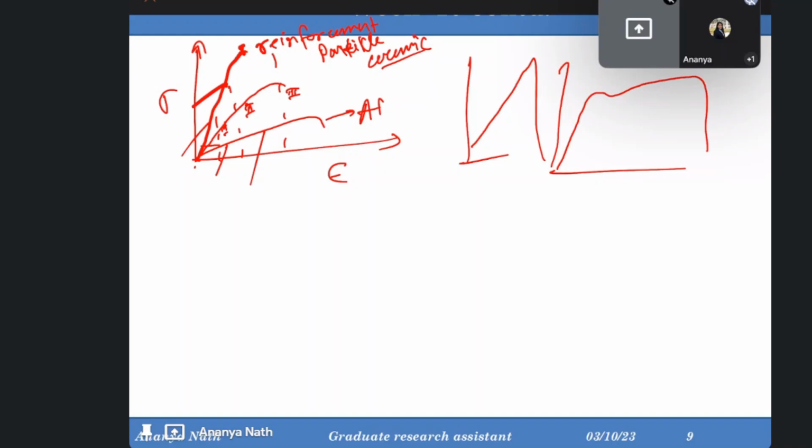It may happen that your elastic modulus critical value is giving one value and you have gone up to that critical value and you are expecting that your composite will go good in a particular application, but it may not go well because the rule of mixture had some assumptions which may not be true for your material.